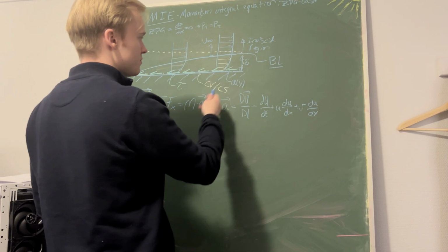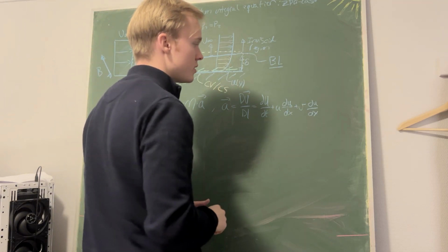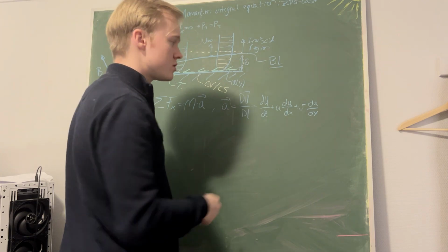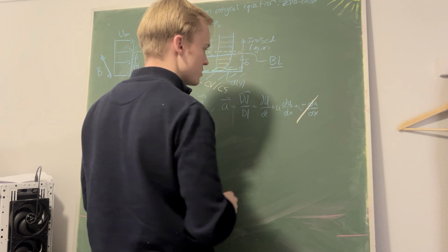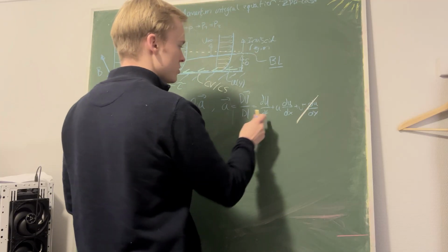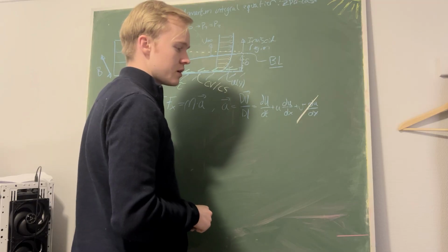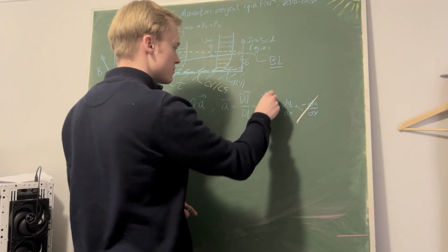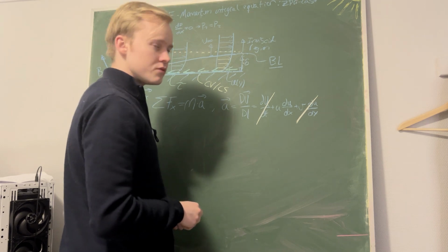So we have to accommodate for the spatial change. We still just have a function u of y, but we only have a u component, so v is still 0, which means that this term goes to 0. We also say that we have a steady state case, so everything with d/dt goes away.